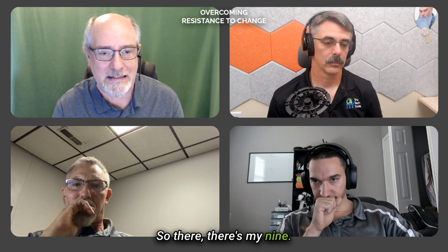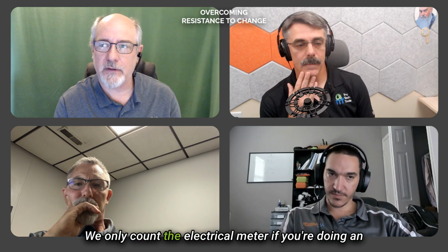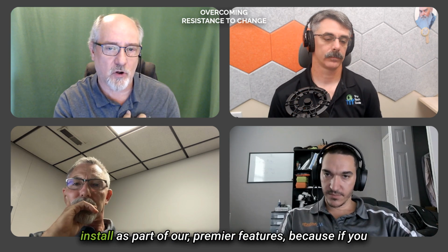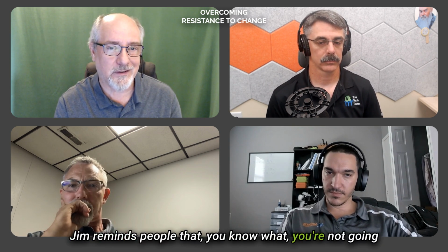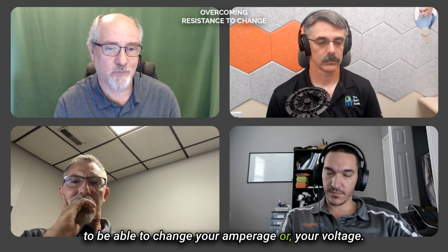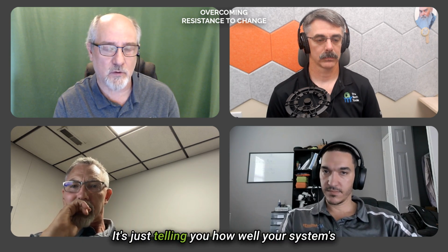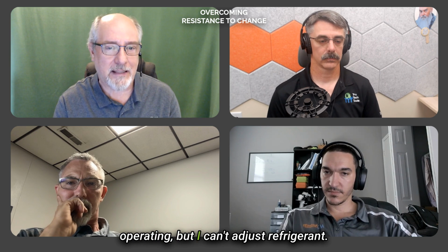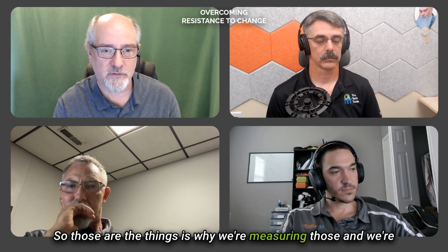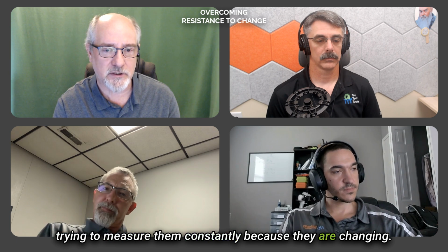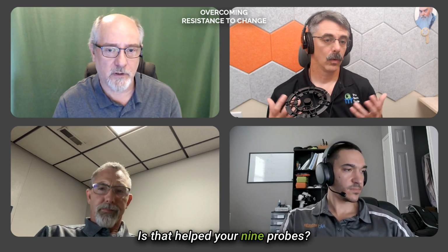So there's my 9. We only count the electrical meter if you're doing an install, as part of our premier features, because if you do an install, we want to capture the electrical service. We don't require it. Jim reminds people that you're not going to be able to change your amperage or your voltage. It is what it is. It's just telling you how well your system's operating. But I can adjust refrigerant. I can adjust airflow. So those are the things we're measuring, and we're trying to measure them constantly because they are changing. Does that help with your 9 probes?